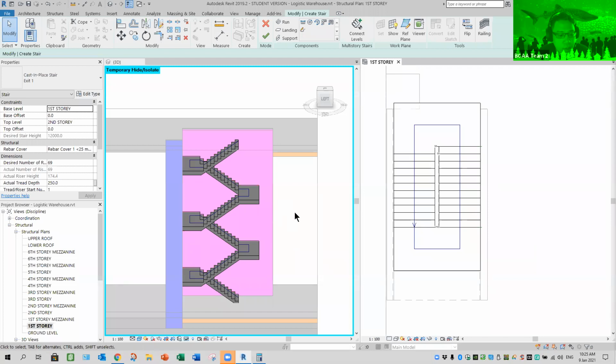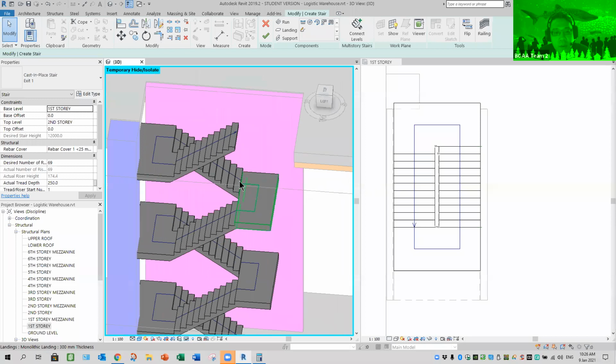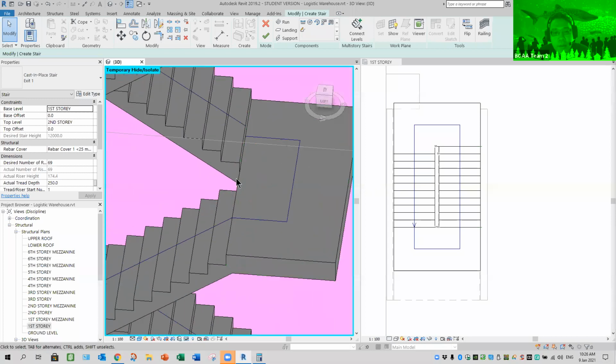For instance, I noticed one thing here: a staircase without a depth here, the design is a bit difficult for the railing to get generated in Archi. Of course, in the real world we can build something like this, but as you learned in Revit Archi before, the railing is always a headache. So I might do some adjustment here because of the space I have. All right, so this is what I'm going to do.